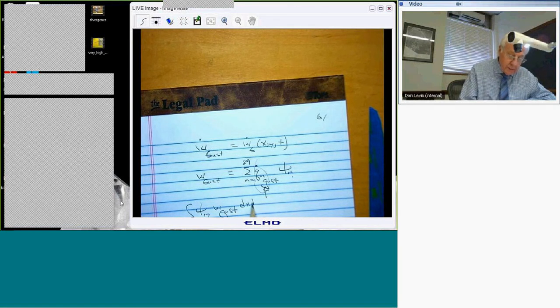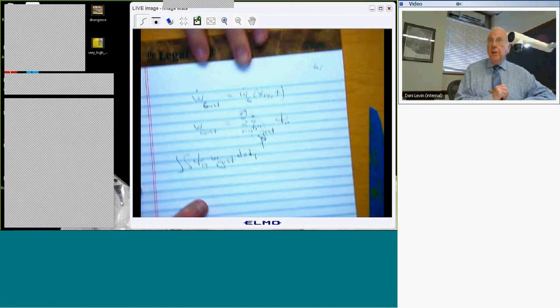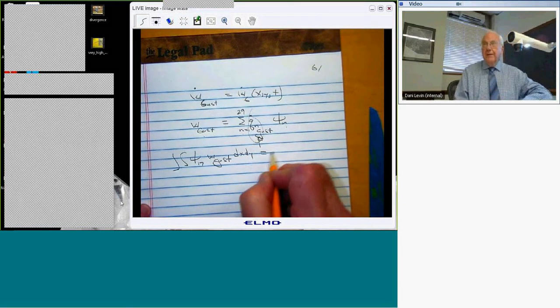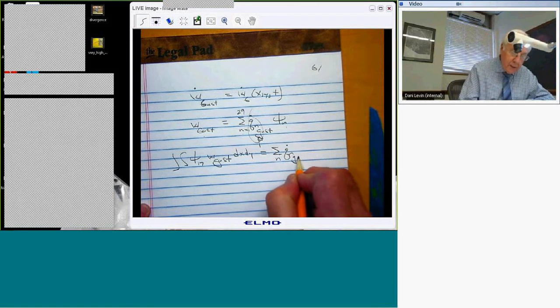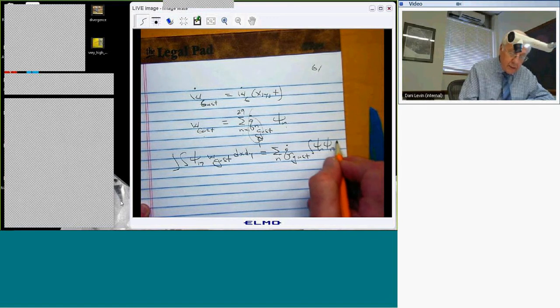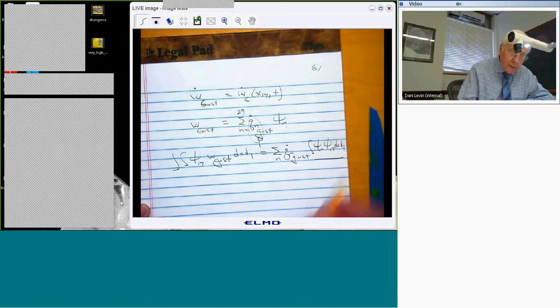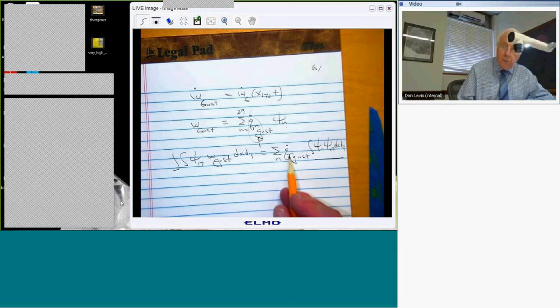And I have to have a double integral, right? And then on this side, I'll have the summation over n, Qn dot gust, integral of psi sub n times psi sub 17 dx dy. What's that integral equal to for a uniform mass distribution? It's 0 unless n equals 17, which means I only have the Q17 term surviving, so this tells me what the Q sub 17 coefficient is. And I do the same thing for any other mode, and I get that coefficient.